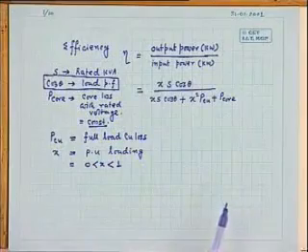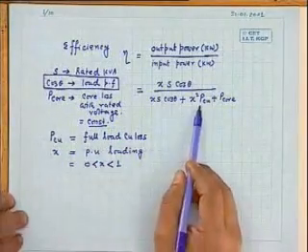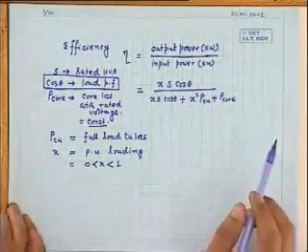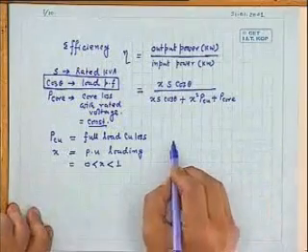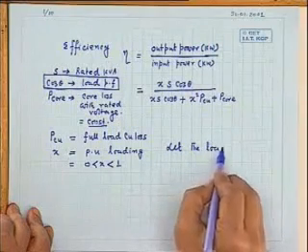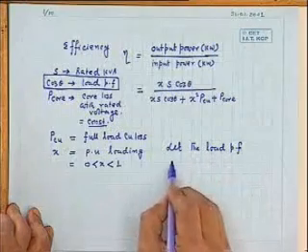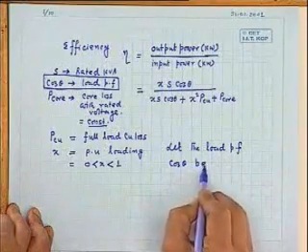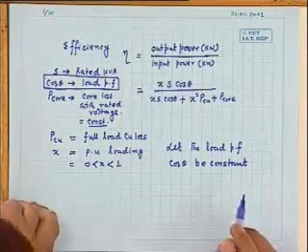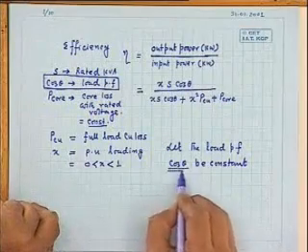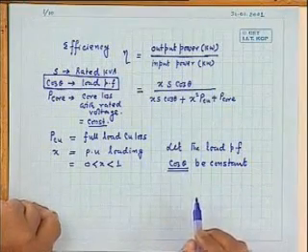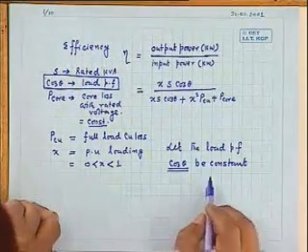Now, under this condition, we note that P copper, that is the copper loss of the transformer, as you vary X, will go on changing, and P core is constant. Now, let us assume the load power factor cosine theta be constant. Okay, cosine theta we are keeping constant, but we are varying the magnitude of the load impedance, keeping the ratio of RL and XL constant.